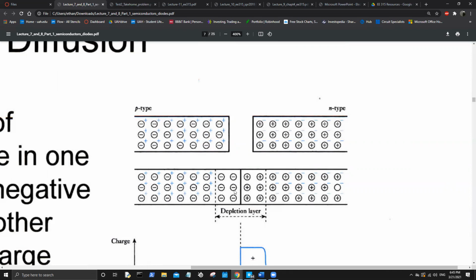This depletion layer fundamentally is intrinsic silicon again. Just think of it as like the demilitarized zone. Fundamentally, your holes from this side and your electrons from this side have touched and come into contact. So the electrons come into contact with the holes or vice versa, and they neutralize. They fill the spot. Now they're happy.